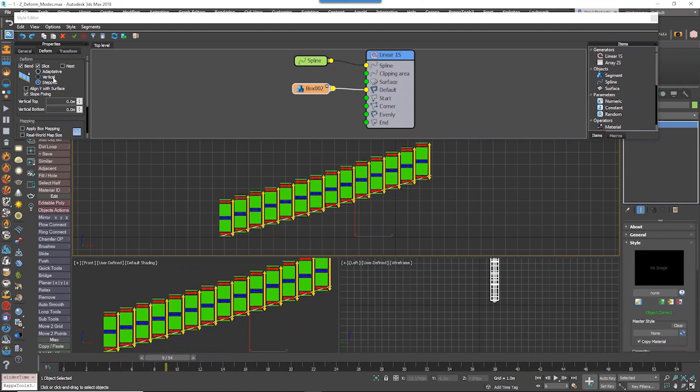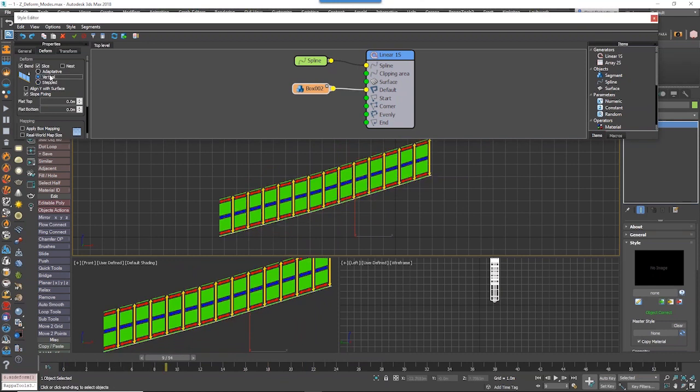Now, where this gets really interesting is that I can combine these. So I can use a vertical mode, but I can step particular parts of this one segment. This is really useful for things like stairs and railings and that kind of thing. I could, for example, say, okay, I want it to be vertical, and then change the bottom so that it's flat, like so. So I've got a stepped bottom and a vertical top. Or you can do the opposite of that, like so.